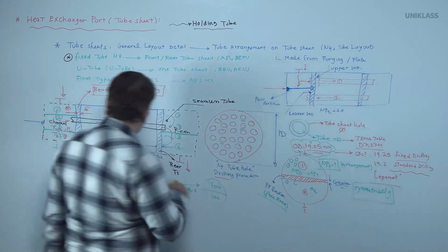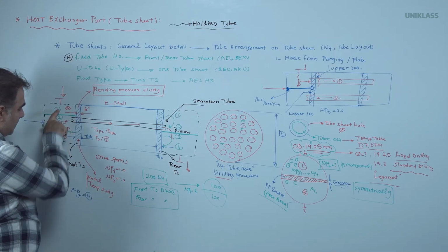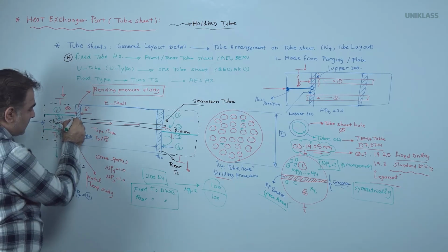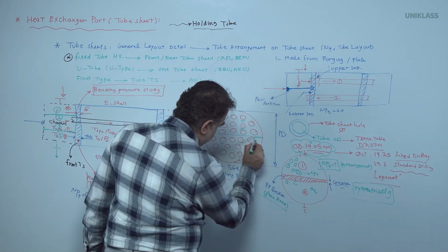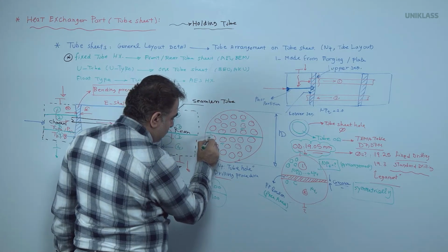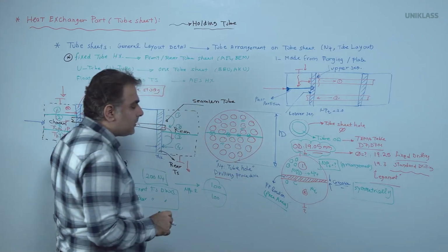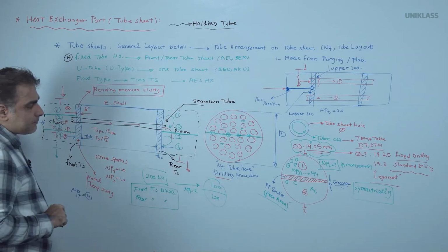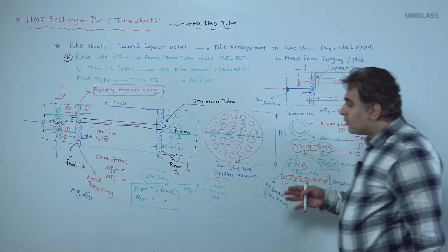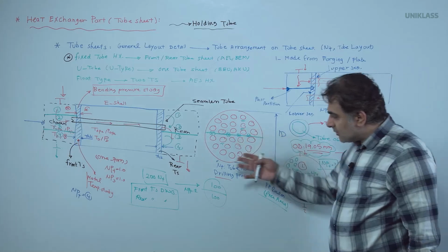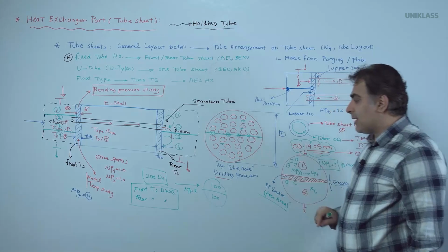Therefore, when we are talking about the heat exchanger passes, we need to know what the installation procedure inside the channel and tube sheet is and what the free area is. This free area may be available here by this segment. We cannot put a tube here. It is forbidden. It is not possible to put one based on the path partition available here. Therefore, when we are talking about the tube sheet layout, it says to us how many tubes are available in the system, what the arrangement of the tubes is, and what the drilling philosophy is based on the availability of the path partition.